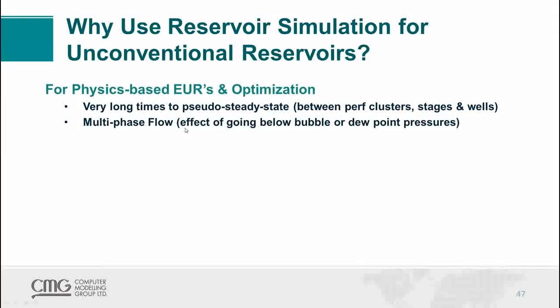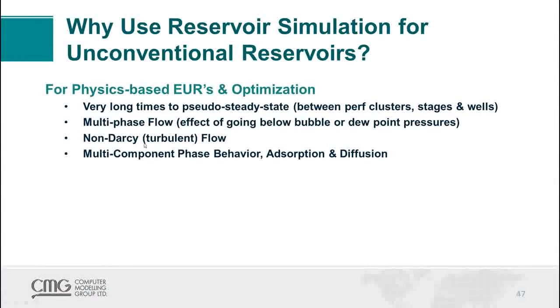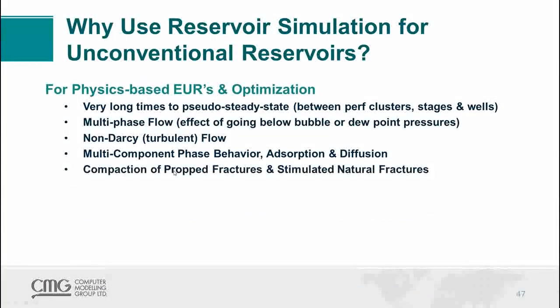Multi-phase flow is occurring in a lot of the shale liquids reservoirs. That really demands the use of numerical modeling. Turbulent flow, especially in the prop fracture conduits as you get close to the wellbore, can be an issue that numerical modeling can handle. Multi-component phase behavior: when you get into near critical fluids, when you start looking at EUR projects, huff and puff projects to recover more oil, you're going to get yourself into a situation where only the numerical models can handle.